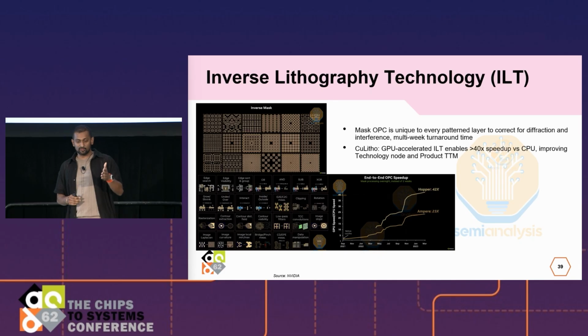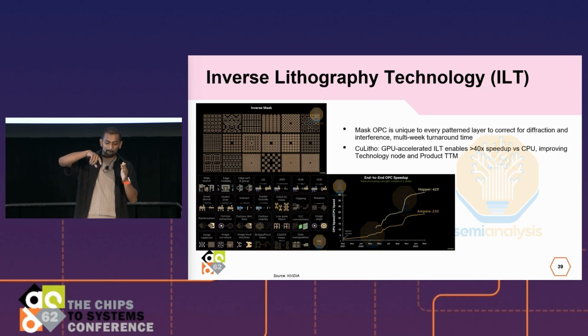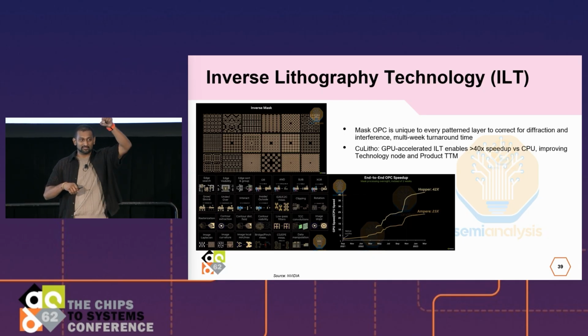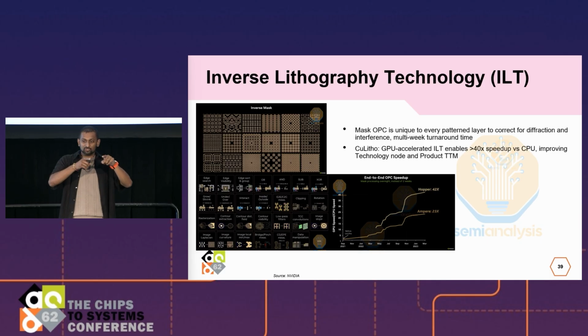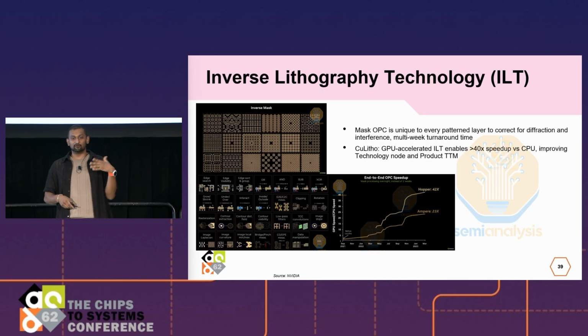So when you're in a lithography tool, you have your design, it goes to GDS, and gets turned into masks. You have all these patterns that you want to draw, but if you want to make a line, that is not the best way to do it. Actually, you want to do other patterns, because of the interaction of the light through the tool and through the mask, through the photoresist, you actually want to not do exactly that.